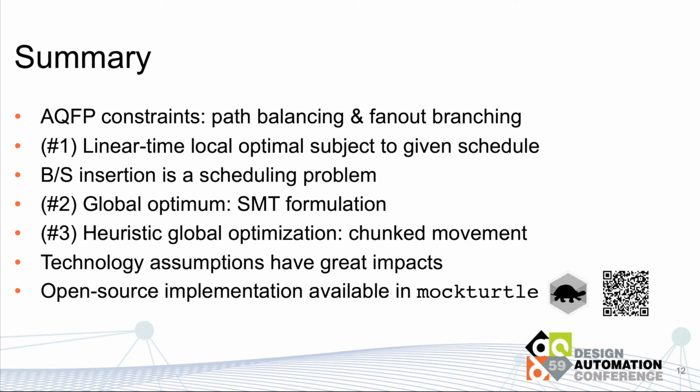To summarize, in this presentation, we learned that AQFP circuits impose two special constraints, path balancing and fan-out branching, and we need to insert buffers to satisfy them. We propose three contributions in this work. First, we have a linear time algorithm to insert buffers that is locally optimal subject to a given schedule.